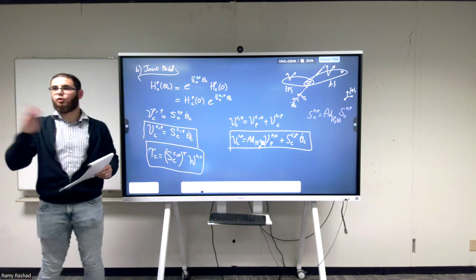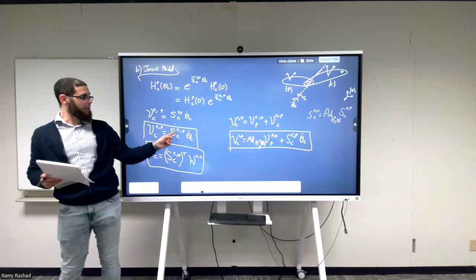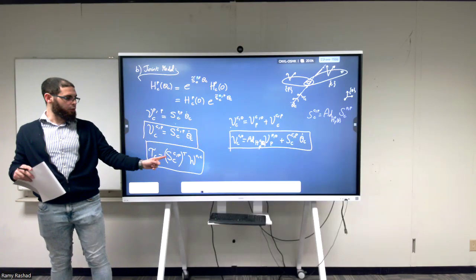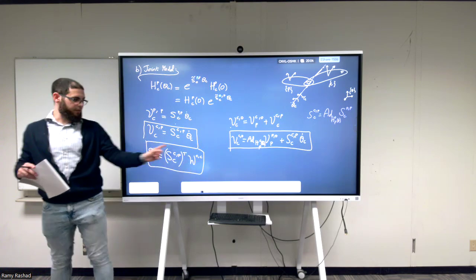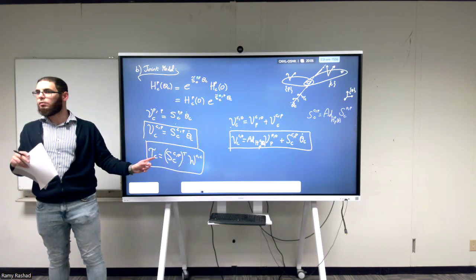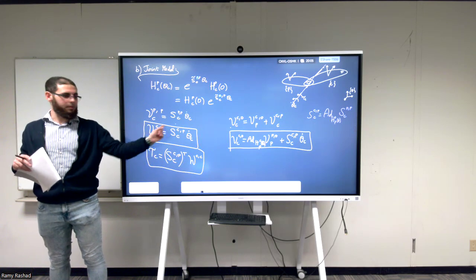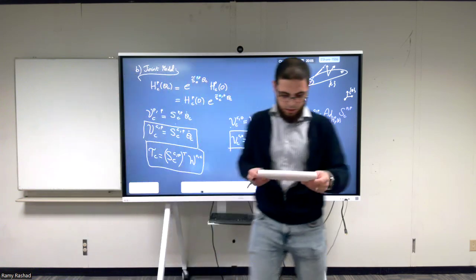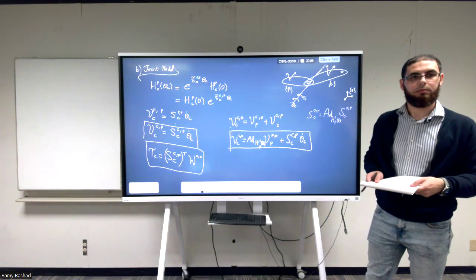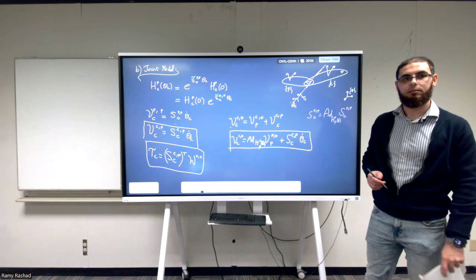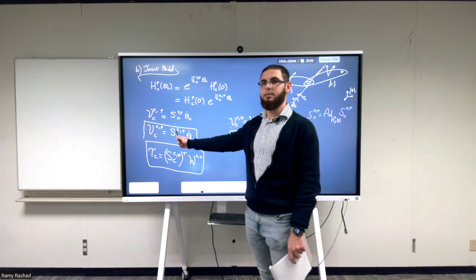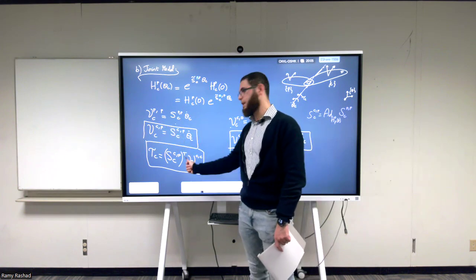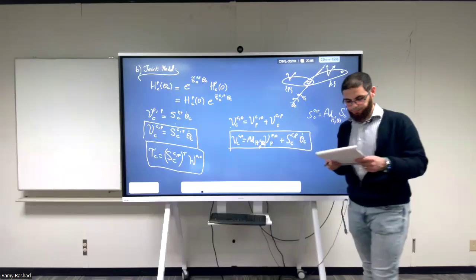And you remember when we talked about duality, okay? This is a map that goes from one number to 6 numbers. The transpose will take 6 numbers and give us 1 number. You see, this is the dual of this map. So this is a linear map, and this is the dual of this linear map, as we talked about earlier. That's just like the Jacobian, but just for a single joint. This is the Jacobian, yes, exactly. This is what we talked about to be the Jacobian. And this is the Jacobian transpose, yes, exactly.